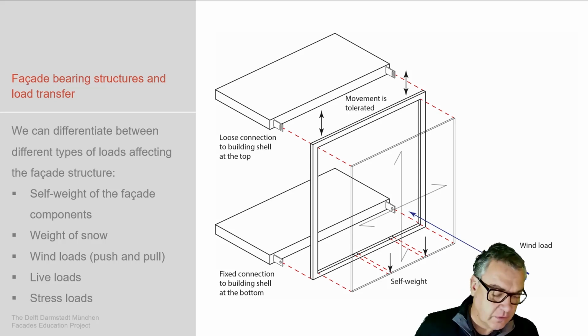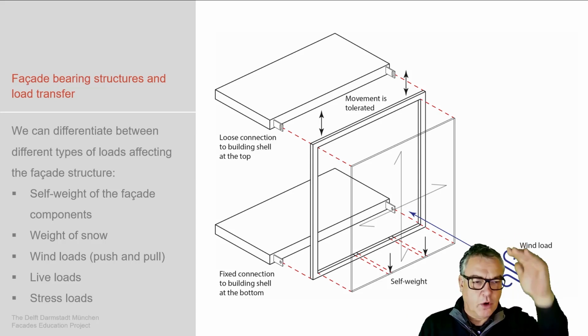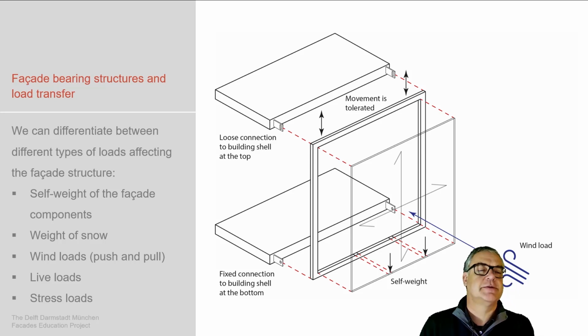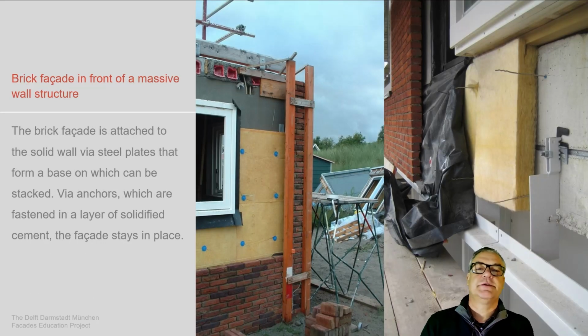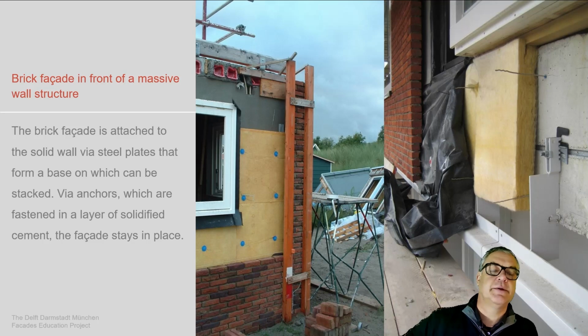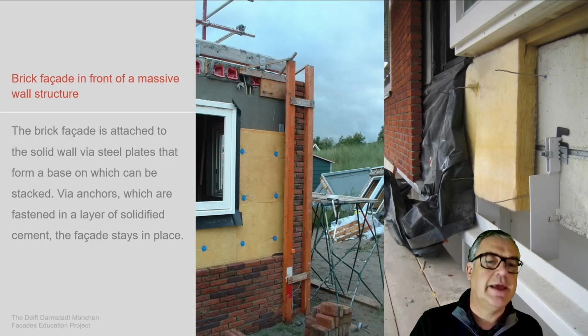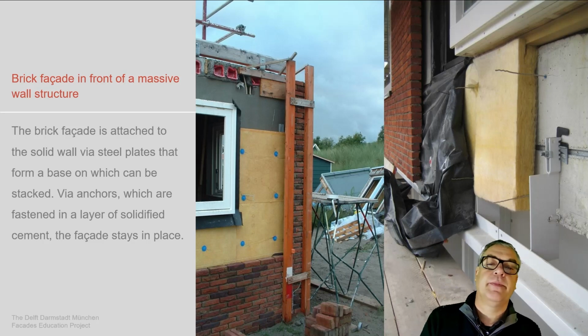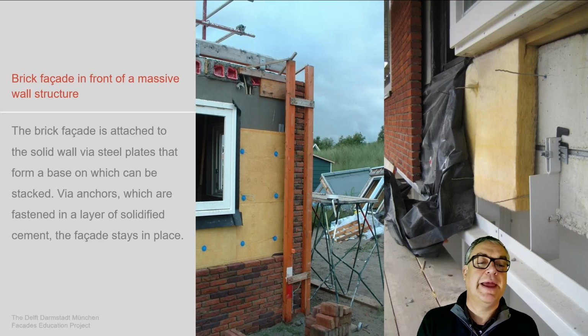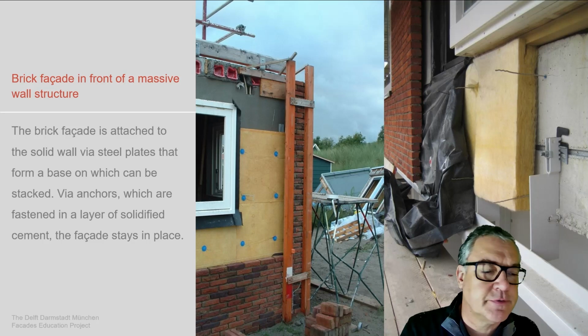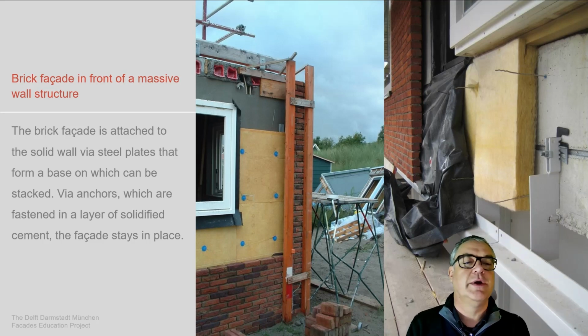But what do these connections look like? We browse through all different types of building envelope facades which we are used to. This is a brick system, which you see on the left side. It is a ventilated cavity brick facade with an inner main structure of concrete, the gray part which we see, then an insulation. And then you see these anchorage plates, which are connected to the concrete and keep the outer layer of brick structure in position so that it doesn't fall over.